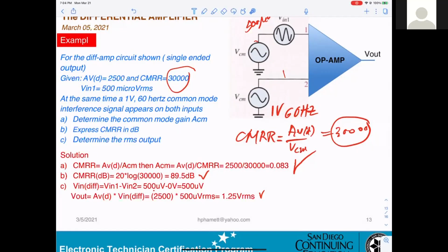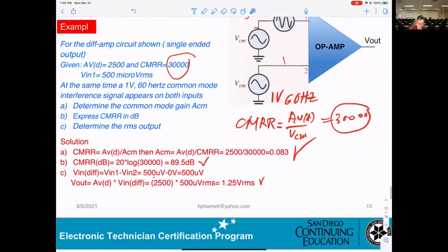I think the point here is that the noise goes through input 1 and input 2, hence they cancel out, and then you end up with 0, and what's left is just your voice that comes out. Exactly, that's why they need a differential amplifier. It has to go through input 1 and input 2 so they can cancel out because they're identical. When they see identical signals, they remove them to a minimum, not affecting your signal. That is the purpose.